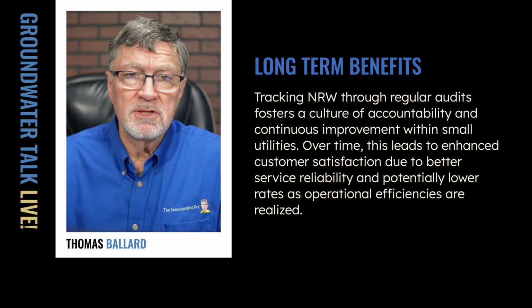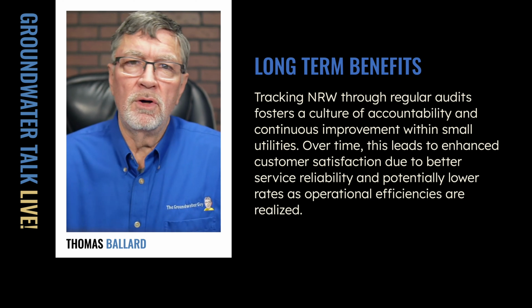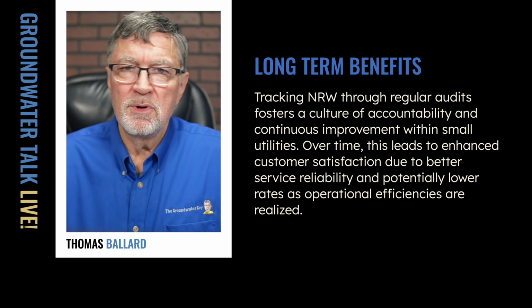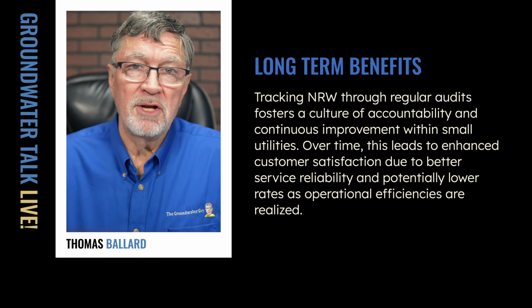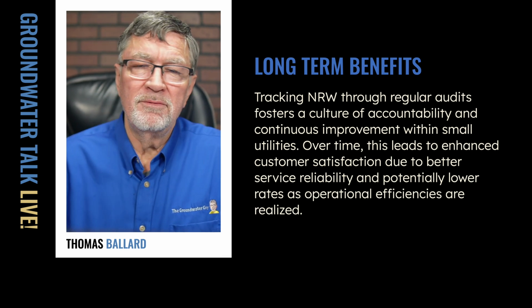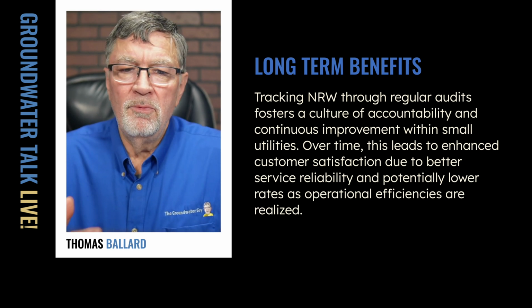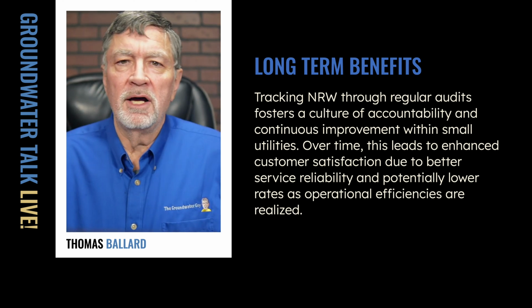So that's important to track that trend, graph it out. So get it all in the spreadsheet, see what that percentage is, and graph it out and see what your trends are, and make sure you're staying on track. All right. So long-term benefits of doing this water loss assessment are really tracking non-revenue water through regular audits.